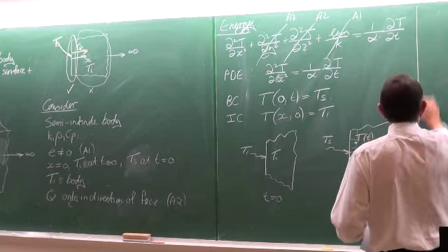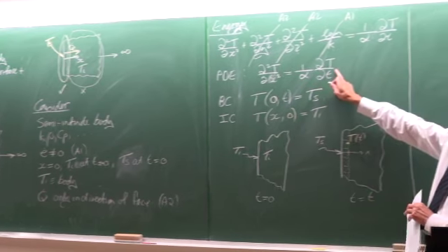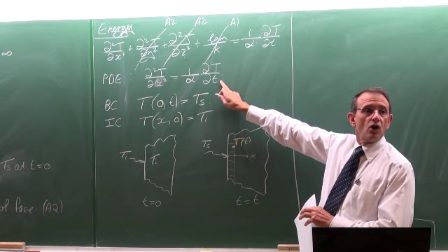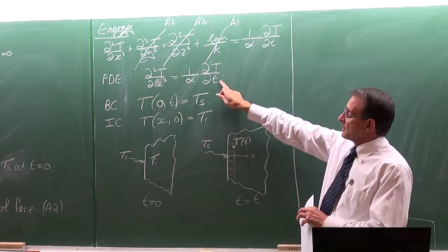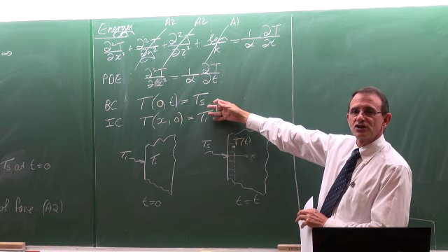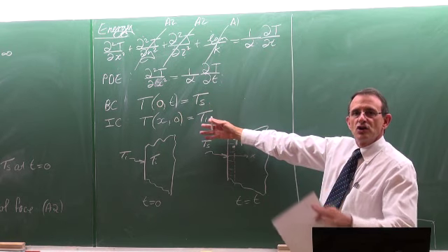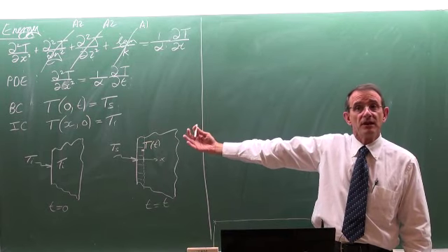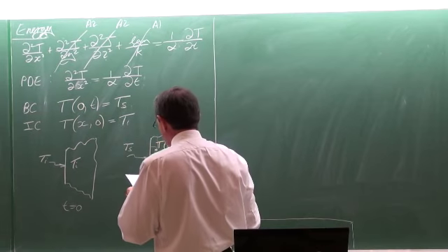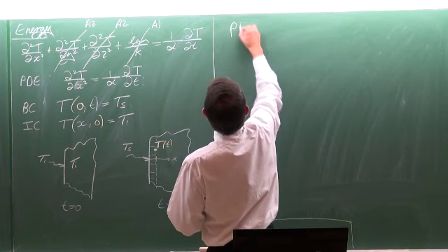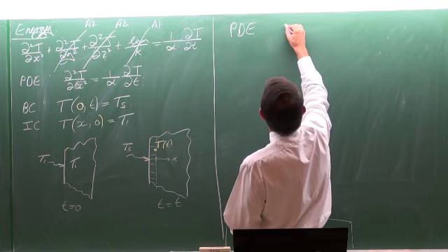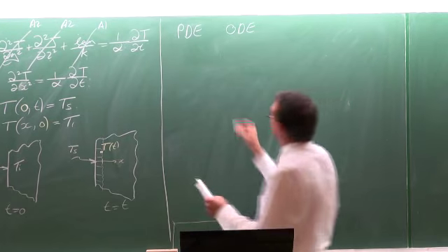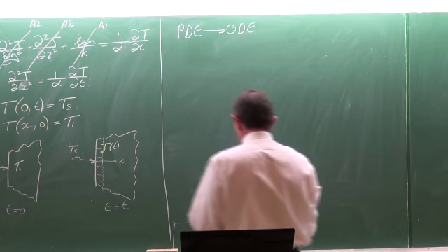Okay. Now this equation that we have here is the same as that we had when we were considering a large plane wall. But the problem is our boundary conditions are now infinite. So the method of separation of variables cannot be used here. And we have to use another method to solve this partial differential equation. And this method changes the partial differential equation to an ordinary differential equation.